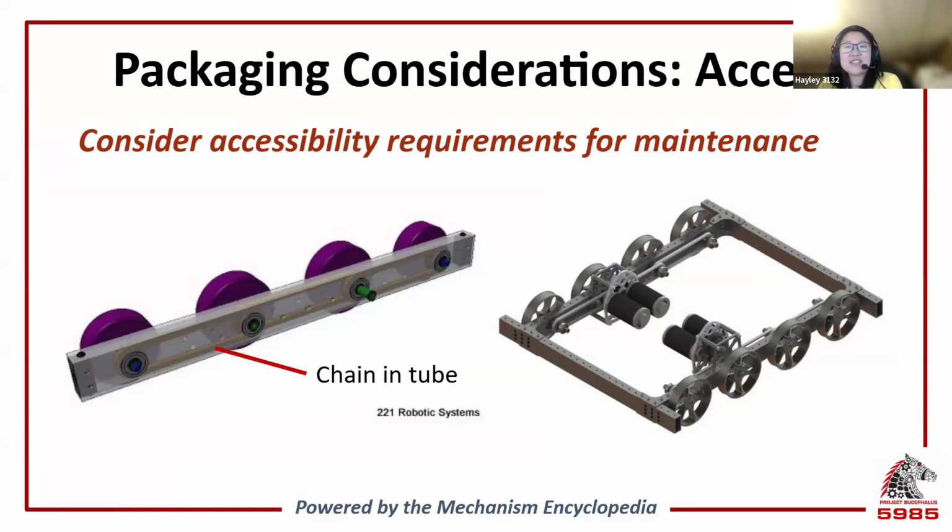Plan ahead to ensure that the parts that need frequent adjustments, like your belts, chain, or even gears, are easily accessible. Components like polybelt, for example, might require regular tensioning or even remaking and reassembling onto your robot. By designing these with access points, you can then make it easier to address issues without disassembling major parts of your robot in the pit.